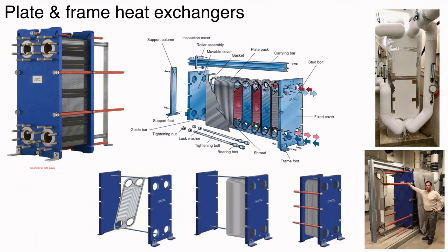Now, here's the big brothers to the brazed plate heat exchangers. These are called plate and frame heat exchangers. Same concept, although this is a unit that is not permanently sealed together. The stainless steel plates here have gaskets around their perimeter, and the idea is basically we're going to assemble a sandwich, a stack of these plates, and you'll see there's a carrying bar up here at the top, and these plates basically slide down onto this bar, and it suspends them almost like a coat hanger, if you will.